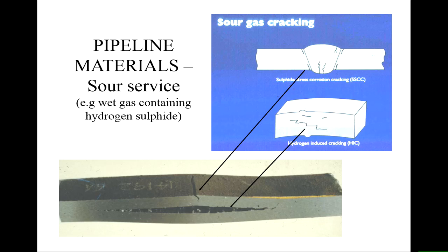What you can see, though, when you measure it is these stepped cracks. And that's very symptomatic of hydrogen because the hydrogen is collected in these inclusion layers, and then the crack just links them all up. And around the weld, particularly around the toe of the weld, that's that part here, in the heat-affected zone, you'll see these cracks running in. There's lots of defects in these regions here, and lots of defects in the weld metal. The crack starts at the surface and tends to run inside, depending on what you've got. And remember that you get a residual tensile stress in this direction due to the cooling. So that's why it opens those cracks up almost perpendicular to the surface of the material.